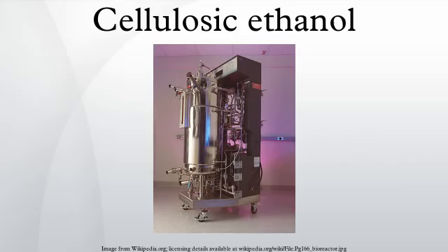The cellulase family of enzymes has a one to two orders of magnitude smaller efficiency. Therefore, it requires 40 to 100 times more of the enzyme to be present in its production. For each ton of biomass it requires 15 to 25 kilograms of enzyme. There are also relatively high capital costs associated with the long incubation times for the vessels that perform enzymatic hydrolysis. Altogether, enzymes comprise a significant portion, 20 to 40%, of the cost of cellulosic ethanol production.